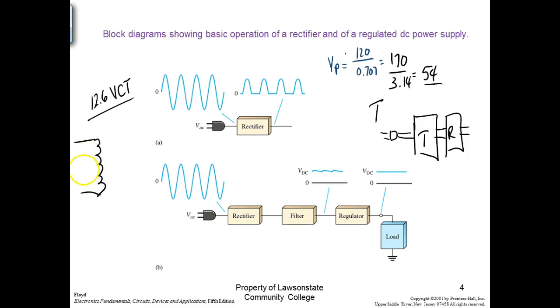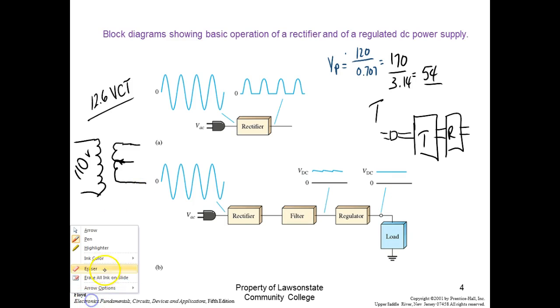So what we got is we got a transformer. It's rated at 110 volts, but we know we're not doing that, so that's what it's rated at. And it says 110 volts over here on the center tap, over here on this side. If we came out all the way across it, so if I use both outside leads, we should get approximately 12.6. If we come across half of it, then we'll get 6.3.